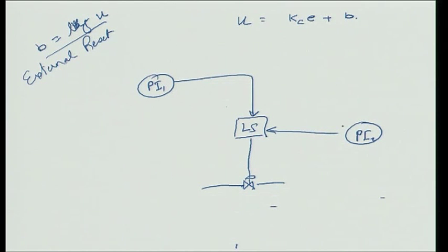Now, when two PI controllers are competing for the same valve, instead of taking your reset action from here and from here, this PI controller will actually be some Kc, some K2 times the error in the second variable, and I have a lag which gets added here.